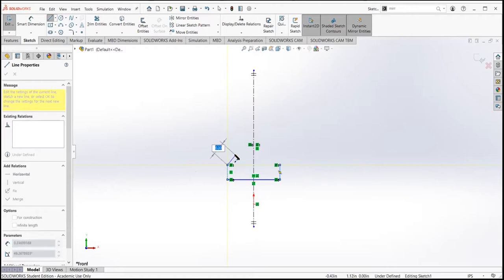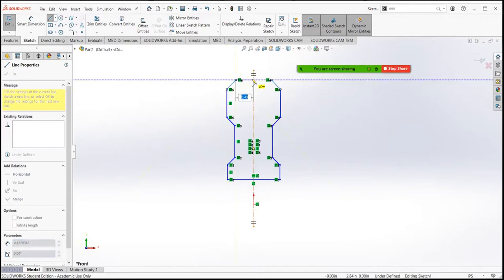To avoid creating this constraint, just hold control, then continue releasing the control, because we want to make sure this is a vertical one. Then go back, because this is angular, so press control and draw it. Then go back here, then hold control because it created 45 degrees, which we don't want. Then close your part.